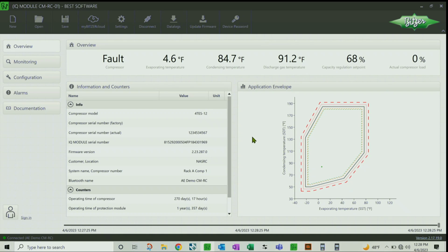If you're not doing application monitoring or you don't have transducers, that doesn't exist because it can't do the math. It can't convert the pressures to temperatures. In real life, this little green dot is going to move around because we're never so stable. The dark green dot is where you are, and the lighter green dots are where you were, and they basically fade away, kind of like an Etch A Sketch. So hopefully your operation is pretty close and precise, not all over the place, but it depends on your application, I suppose.